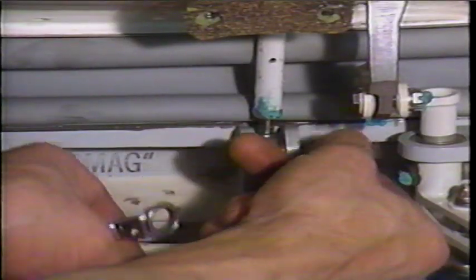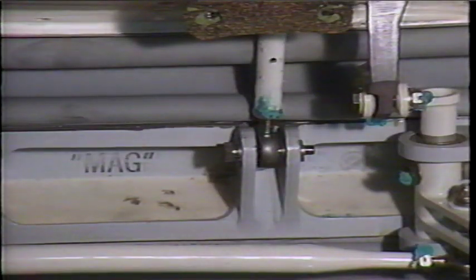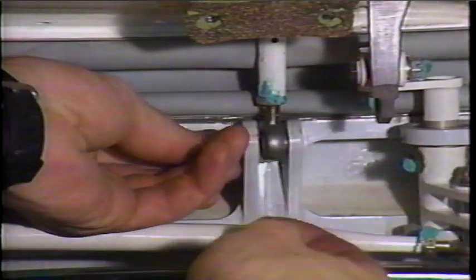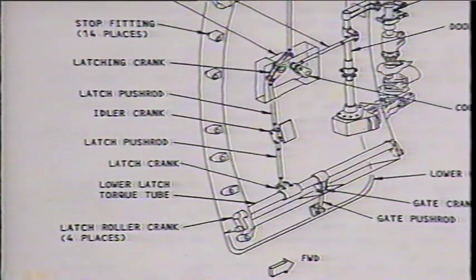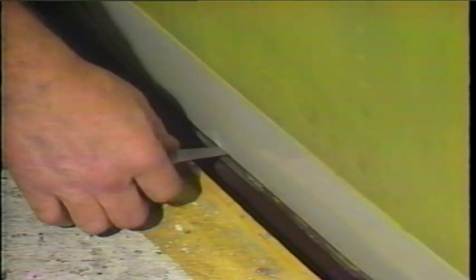Remove the bolt, washer, bushing, and nut to disconnect the gate push rod from the gate. Rotate the gate to the closed position with the gate bearing against the door threshold. Adjust the gate push rod to connect to the gate. Adjust the push rod to the nearest 1/2 turn of the rod end. Insert a 5/1000 inch thick shim between the gate and the threshold.